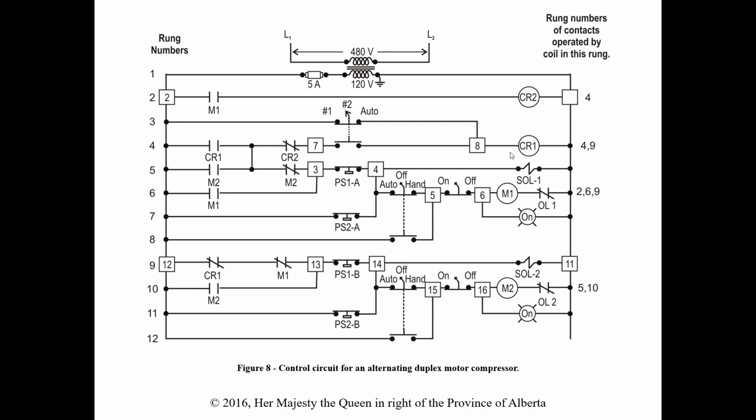So then this figure says figure 8 is a more complex motor control circuit for a compressor driven by 2 motors. Alternate motors will drive the compressor each time it operates, and both motors will run if required. Notice the numbers on the side of the schematic. Okay, so that's these numbers right here. Those along the left-hand side of the drawing are the rung number. So that's the number of the rung of the ladder style schematic.